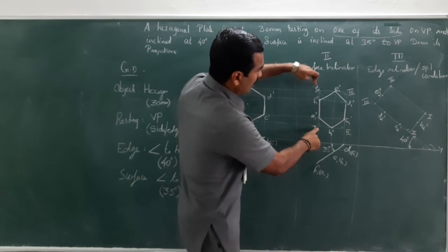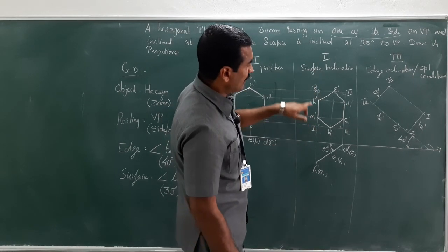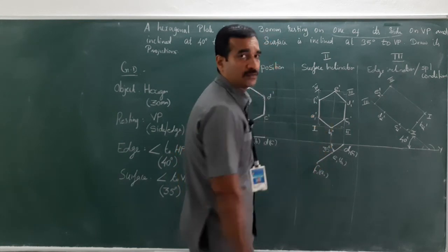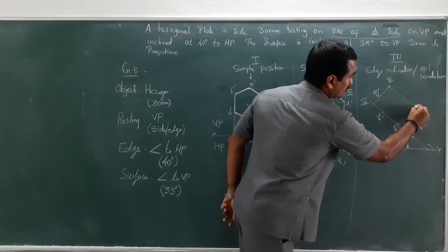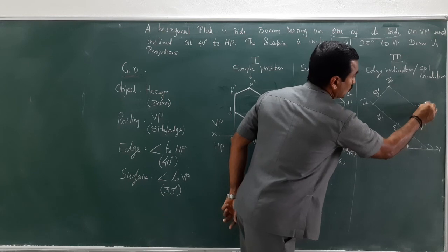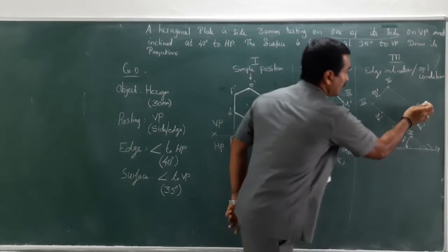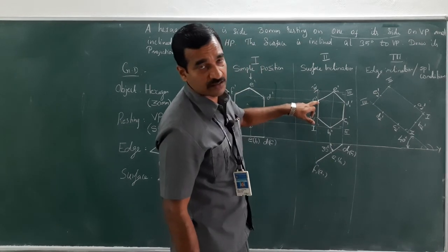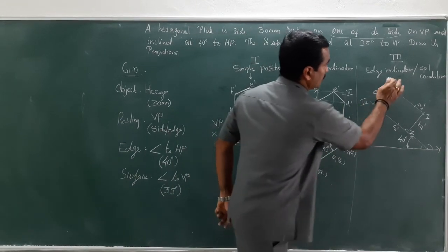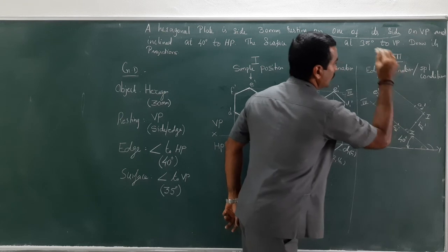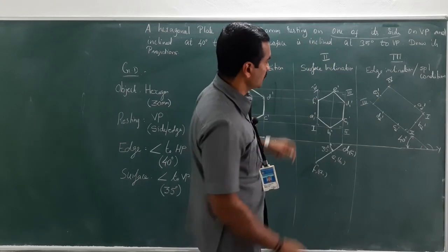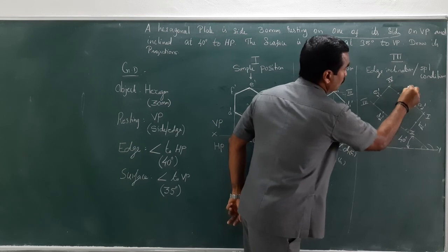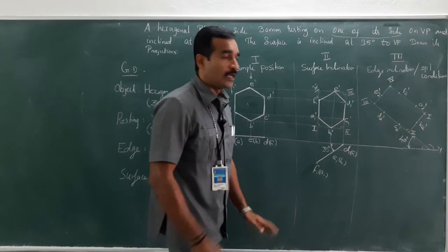Now, between 1 and 4, I have A1 dash and F1 dash. Measure it from 1 to A1 dash. Cut an arc. This becomes A2 dash. Now, measure it from 4 to F1 dash. So, this is 4, right? So, 4 to F1 dash and keep it at 4, cut an arc. This becomes F2 dash.